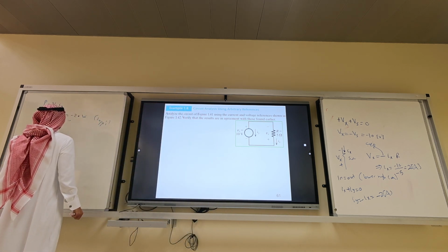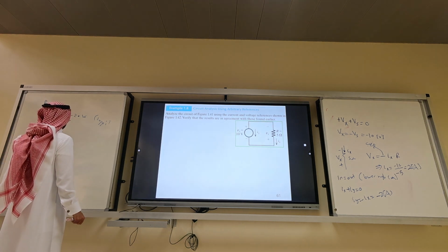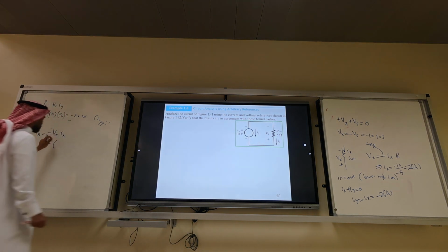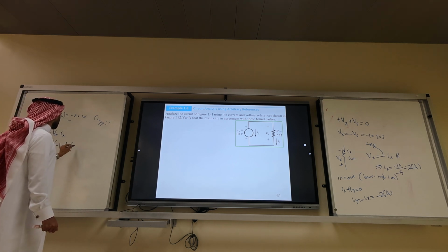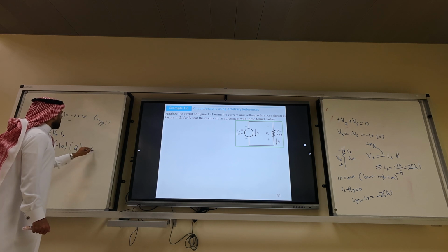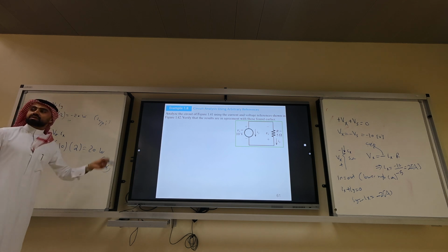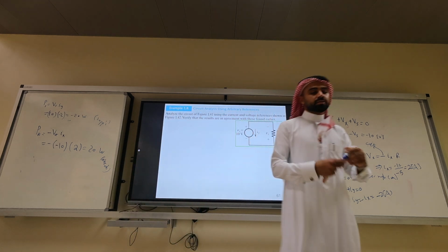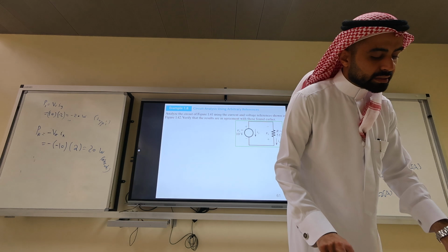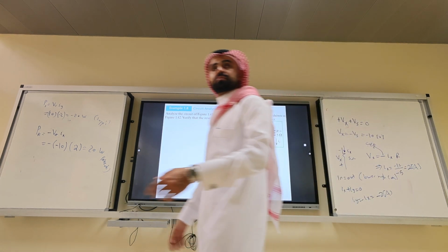Minus Vx times Ix. What is Vx? Minus 10, right? What is Ix? 2. 20 watts. Is this absorb? Absorb. Same results, even if we change the directions of the voltages and the currents. Okay? Get it?